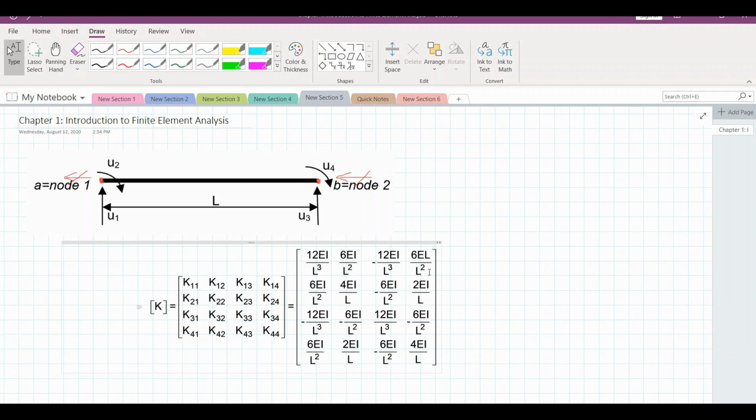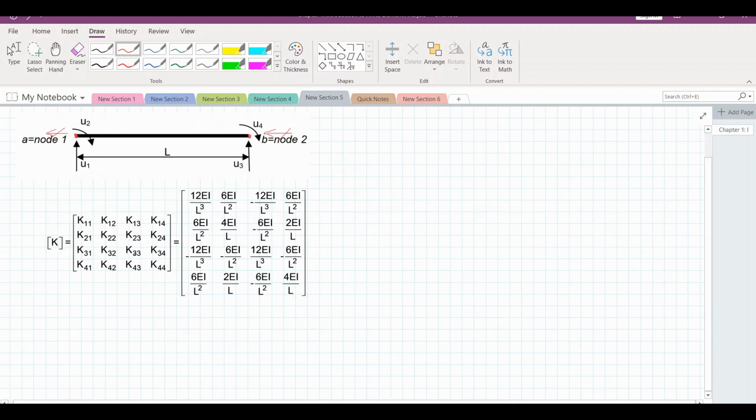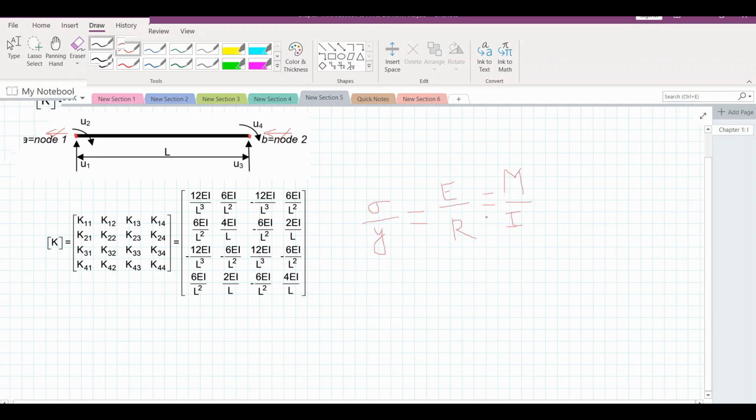We all know that the stiffness of the beam is given by this equation. So we'll be using this matrix in order to solve a beam with different boundary conditions and different loading scenarios. Solving means we tend to find its displacements and reaction forces here. In ABAQUS or in finite element analysis, it will be difficult to obtain the bending moment diagram here. Generally, we'll get stresses, and these stresses have to be modified using certain equations to obtain your bending moment diagram or shear force diagram. We'll also learn how to do that using the beam bending equation.